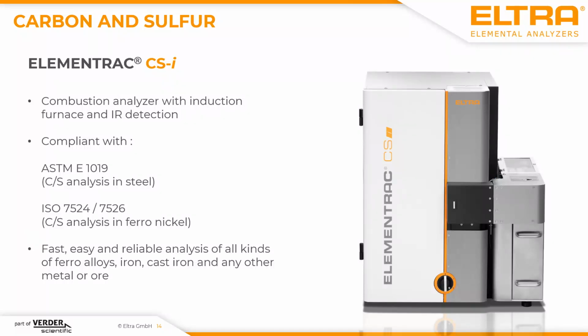Our carbon and sulfur analyzer with induction furnace looks like this. It's called Elementrac CSI, and it's a combustion analyzer with induction furnace and IR cells for detection of CO2 and SO2. It's compliant to all relevant international standards, for example ASTM E1019. This is relevant for steel analysis, and of course it's also compliant with ISO standards which deal with CS analysis in ferroalloys, here ferronickel. It's very easy to use, and on the left side of this picture you see the analyzer, and on the right side you see an optional autoloader. These units would be suitable for analysis of steel, and of course also for the analysis of any kind of ferroalloys.